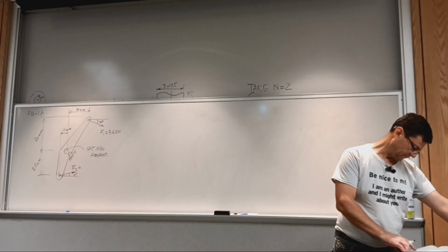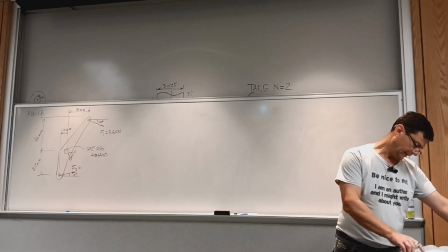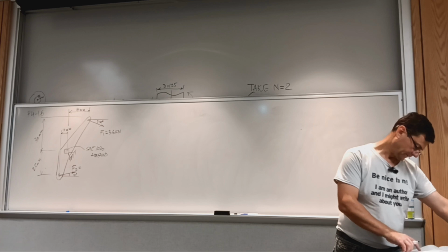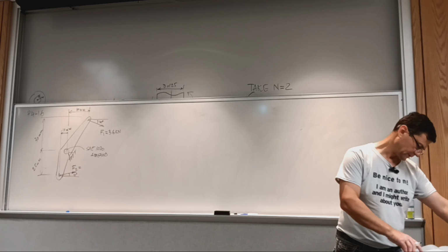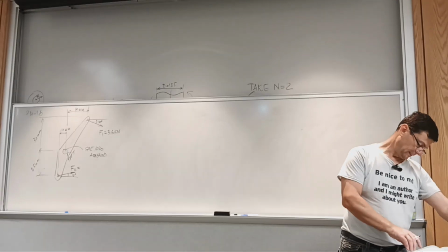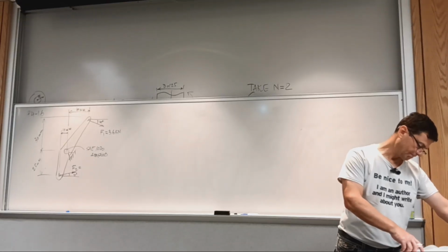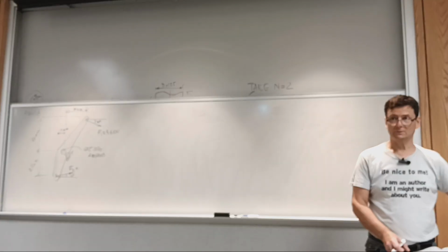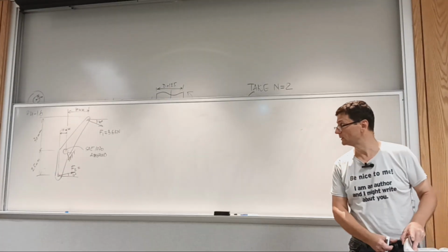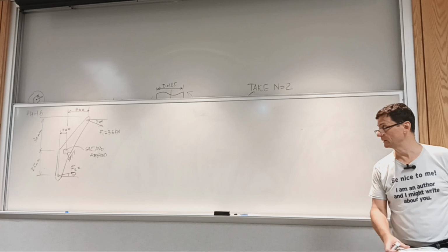And I'm looking at the beryllium copper. And does it give the percent elongation? So soft, hard. Well, maybe they wanted the soft version. The hard version is only 4% elongation, and that means it's a brittle material. Yeah, the soft type is 20% elongation. But I switched to a SAE 1020 annealed.